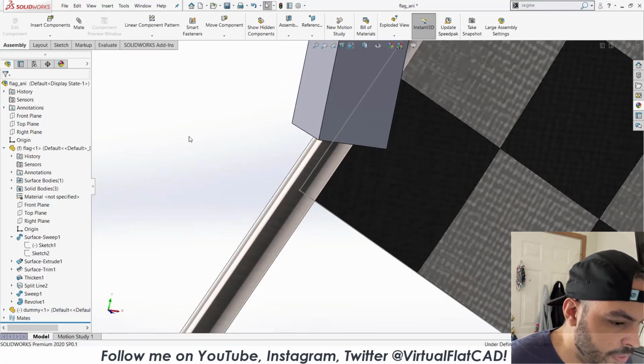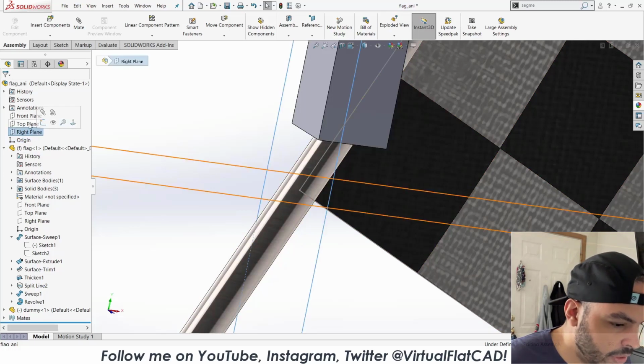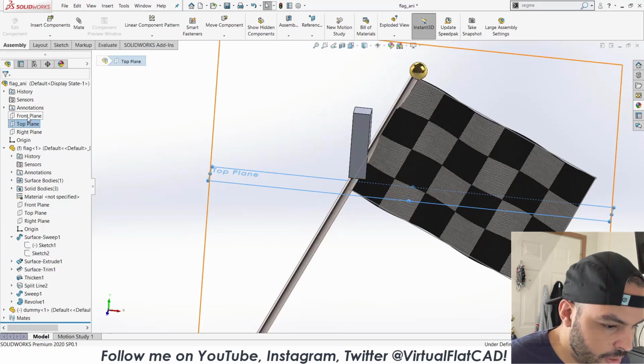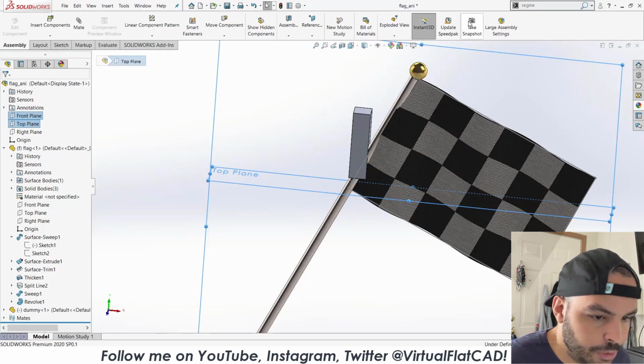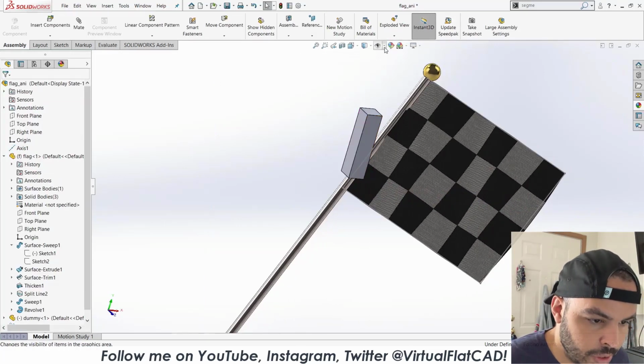I think what would help, there's the origin, I would like an axis to go directly through. So in the assembly, let's grab the top and the front plane, go to reference geometry, axis, get us an axis. And the axis is hiding.